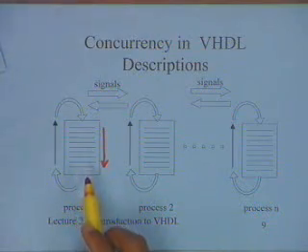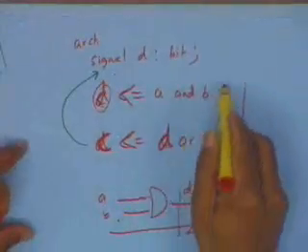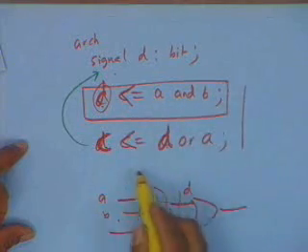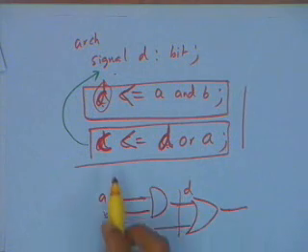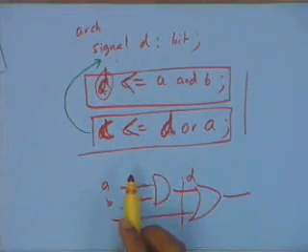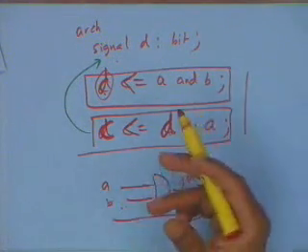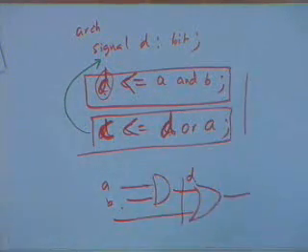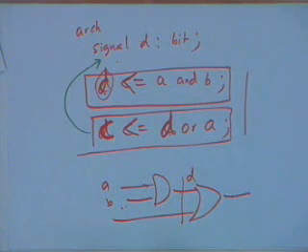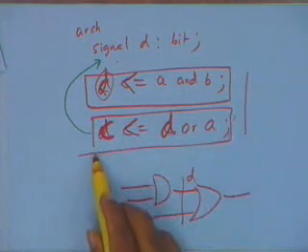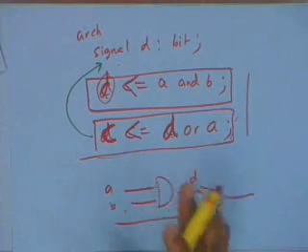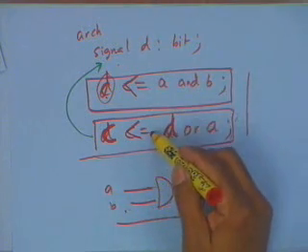If you relate to what I wrote before, this is one single process and this is another single process. I have not written, so there are two ways of writing a process. Once you can write it using the syntax VHDL provides, saying process, where you say the process begins, give the name of the process and so on, and then you say the end process has ended within the body. But a concurrent assignment written without anything else is also a process by itself. So it is like one process, there is like another process.